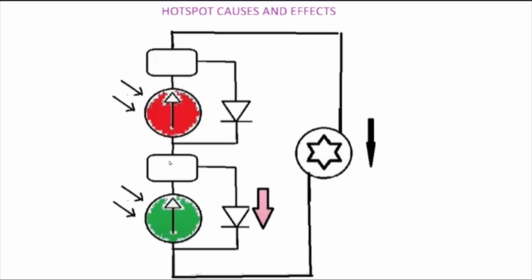And in this case, this good cell can't get through here because it's a one-way valve, and it can't get through the bad pump because it's not pumping, but it's pushing against it, and this can create a hotspot, or an area of strained flow in this area, and in real solar panels that can actually cause the cell to physically heat up.